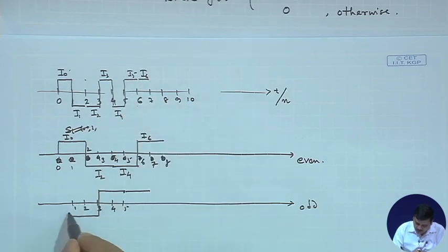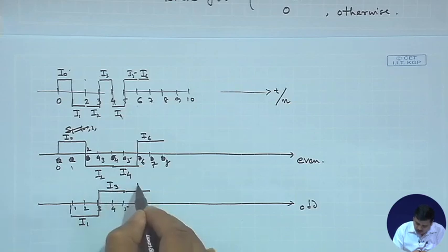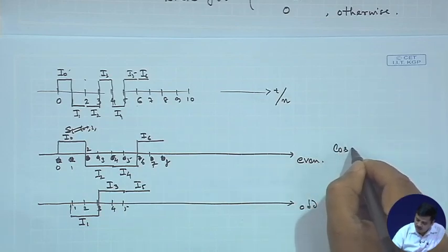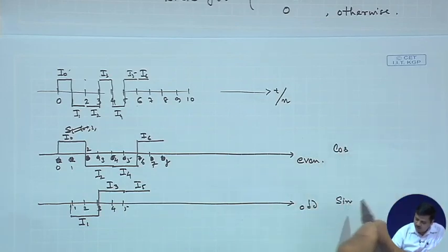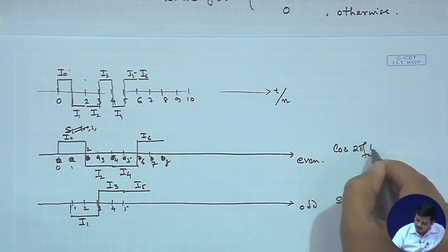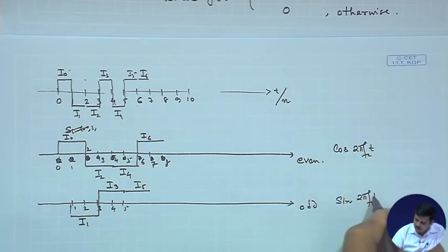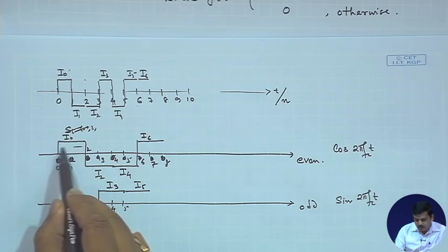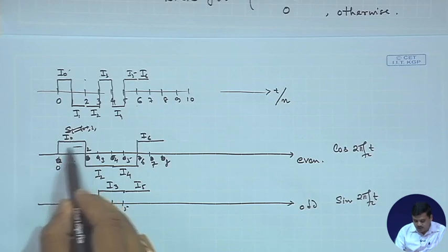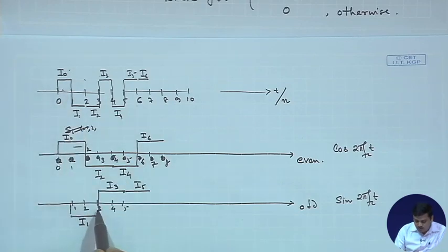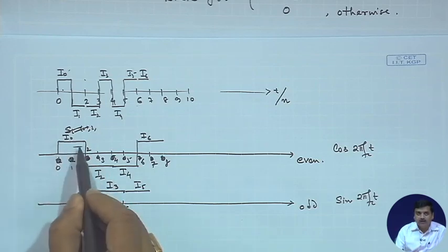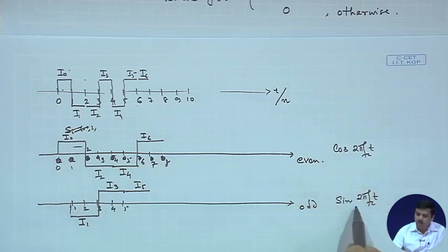So, here I get I5. What you see is this is I1, this is I3, this is I5, and I would modulate a cosine with this and a sine with this, right. If I am going to do this, each symbol duration becomes twice the period T, but in a 2T interval I am sending 2 I values overall, one along the I channel, one along the Q channel.